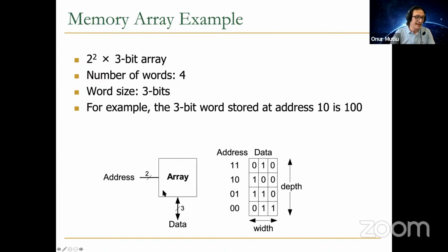Okay, so here I should say that the row size is only 3 bits, right? But your row size in DRAM, for example, can be 8 kilobytes. So you may, for example, have 16,000 rows, and 8 kilobytes row size in each row. Okay, but your data out may still be only 64 bits, for example. You may get only 64 bits out of that 8 kilobyte row, or 64 bytes out of that 8 kilobyte row. Basically, you select or you multiplex the data, the column that you want out of that memory.